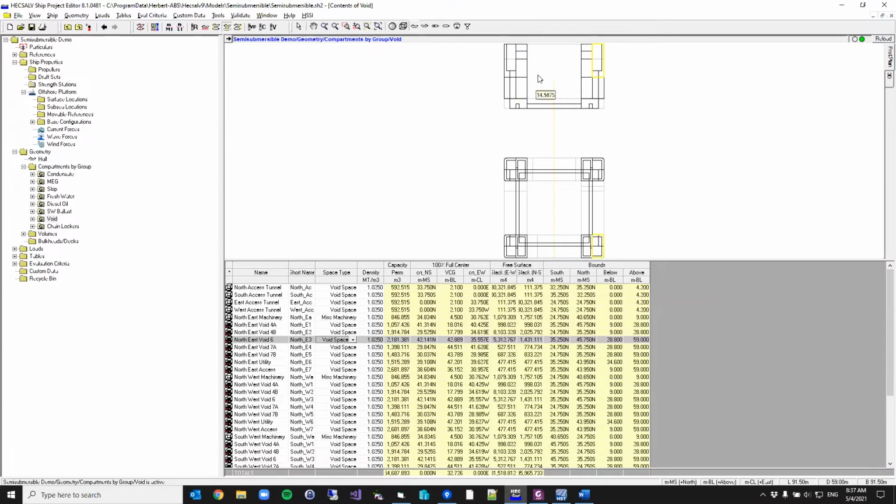And then there's another big flat here at, I think, 28.8. So any damage around this is going to be hitting both the bottom and the top and any combination of those. So when you put a damage analysis together, you're going to have different damage cases based on the draft itself, and you need to know which draft range the draft cases themselves are applicable for. So for what I've put together, I've primarily focused at understanding the requirements around this flat and understanding the requirements around this flat.